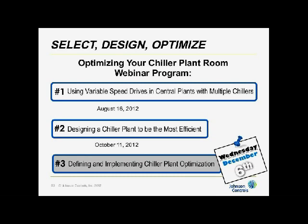Let's see what else. How would you optimize control VFD condenser water pump and VPF systems? How to balance flow over chillers if they have a different rated capacity? Well, you could put a pressure sensor and vary the speed depending upon what chillers are running. You could have an algorithm to vary the speed with load, meaning to maintain delta T across the condensers.